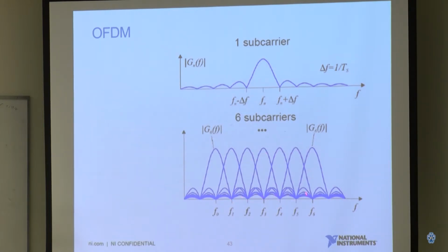By that time, the interference to each carrier will be minimum. So they force the signals onto particular frequencies F1 to F6, like sub-carrier modulation. This is why they call it OFDM. The benefit is you can minimize the interference with multiple carrier signal transmission.